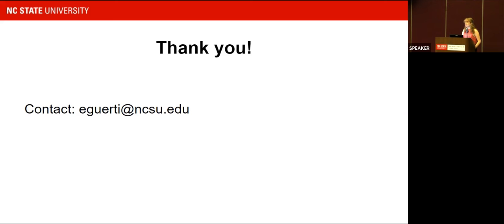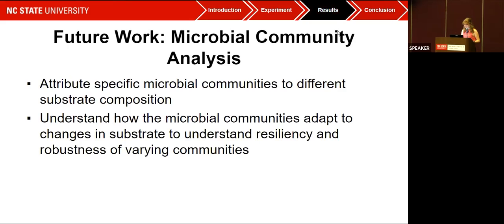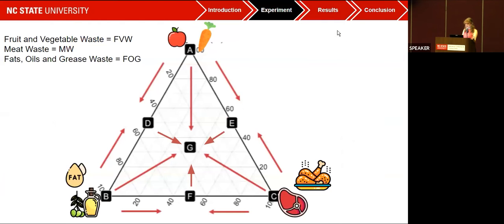Yeah. So I loaded initially that 40 grams of COD of, we'll say protein, the protein reactors. And then for stage 2, some of the reactors were loaded from C, which is protein, some of them were loaded to E and F. So those reactors that went towards E were fed 20 grams of COD, so half of the volume loading rate of protein. So they were getting some protein, and the rest of it, that 50%, was coming from the COD of fruit and vegetable. Okay. Does that answer your question?